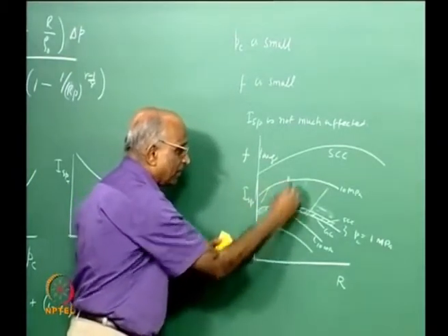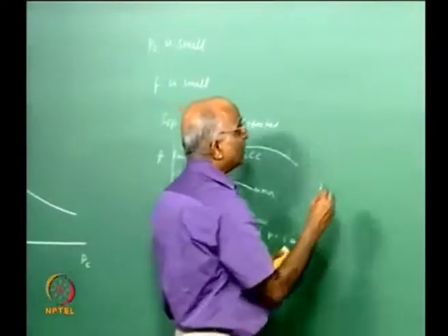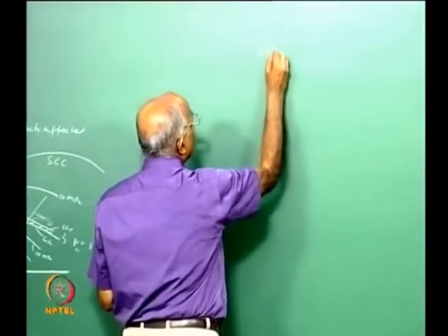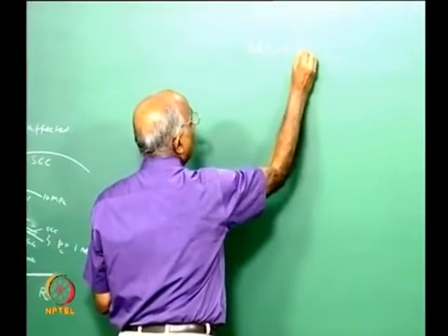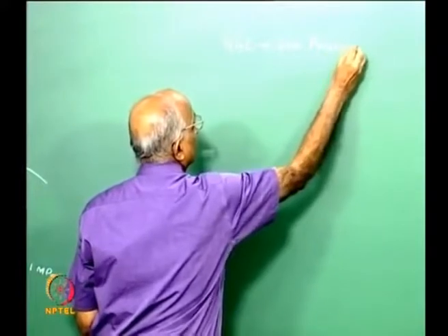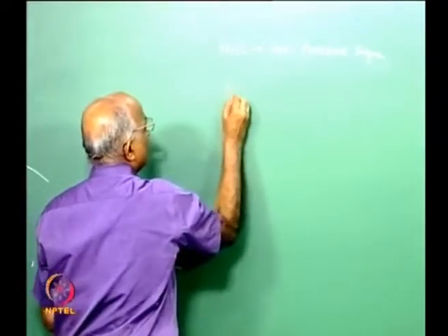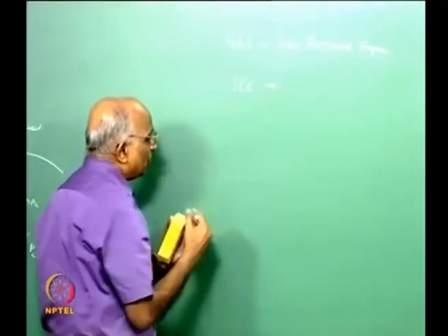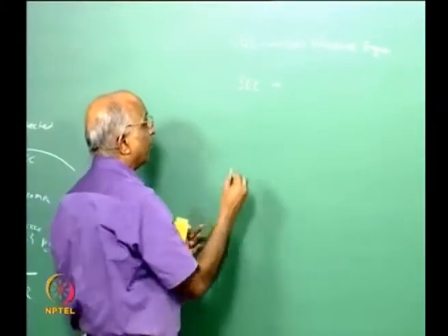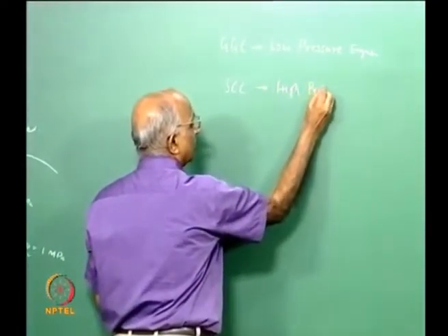Therefore, I can say that a gas generator cycle is more suited for low pressure engines, whereas the stage combustion cycle or expander cycle, which uses all the propellant in the main chamber, is more adapted for high pressure engines.